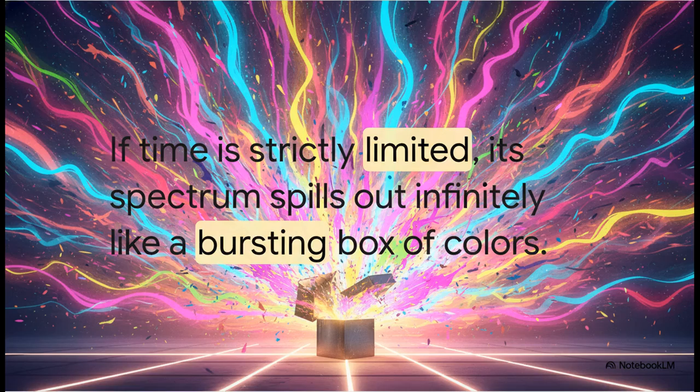Let's try to visualize this trade-off. If a signal is strictly limited in time, meaning it starts at 0, it turns on for just a brief, tiny moment, and then goes perfectly back to 0, its spectrum absolutely must spill out infinitely into the frequency domain. Imagine you've got this tiny, finite animation box, right? But the second you open it, this endless, infinite array of colors just bursts out everywhere. The sharper and shorter your time pulse is, the wider and more infinite its frequency footprint becomes.